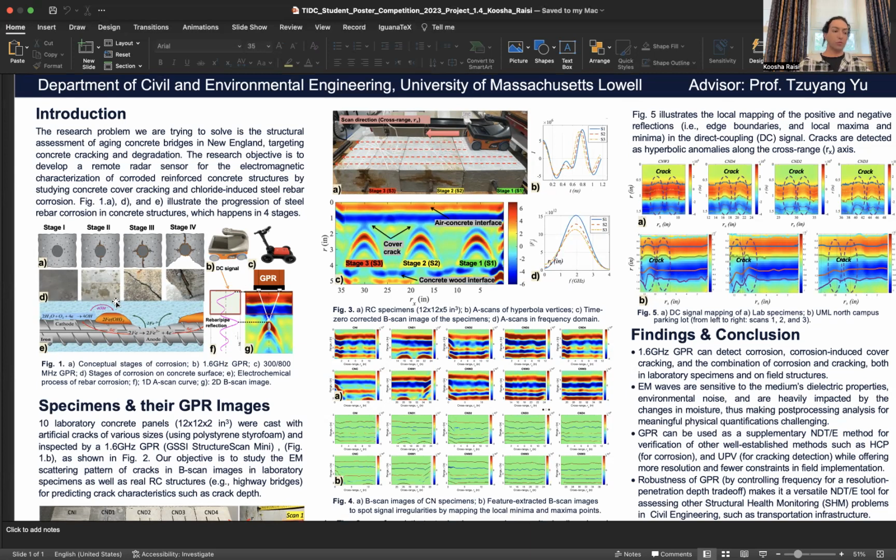The first one is stage 1, which we call the intact, so to speak. But it's not completely intact, as this is a stage that we call hydraulically permeable, as the hypothesis is that the pores are interconnected and there is a pathway for moisture to get in, for chloride ions to move freely and have this electrochemical process.